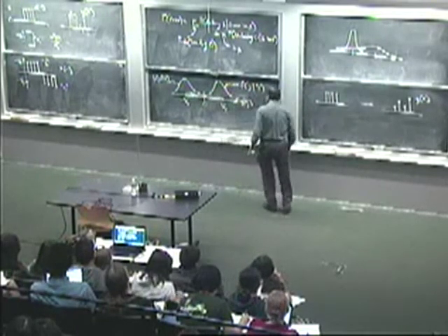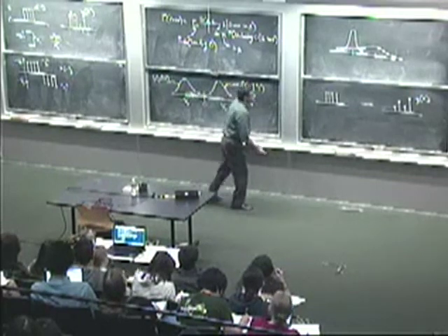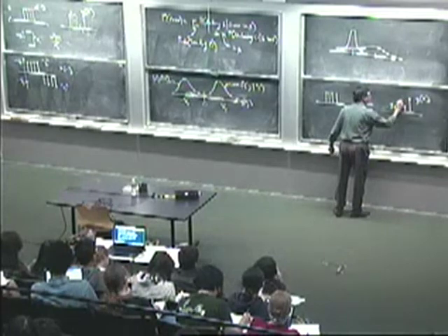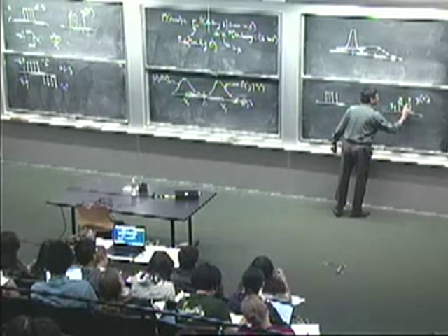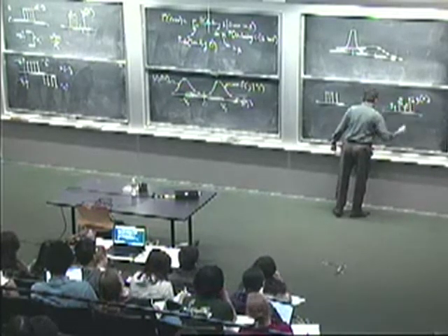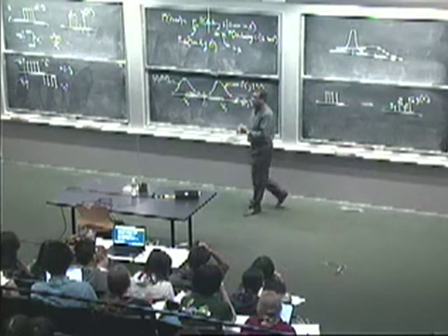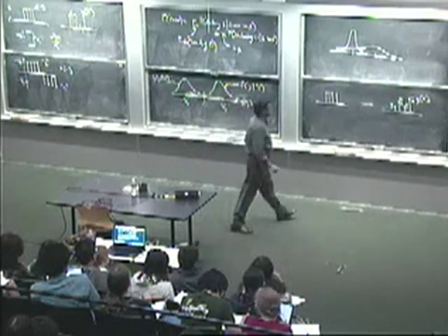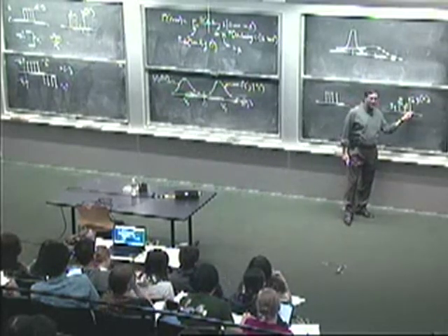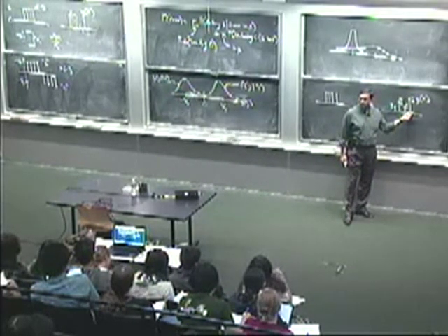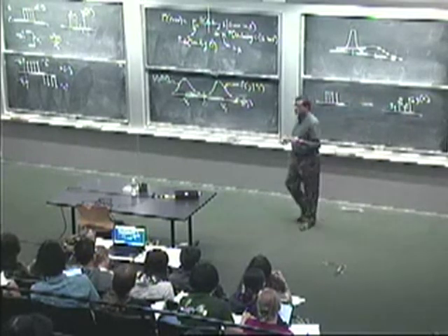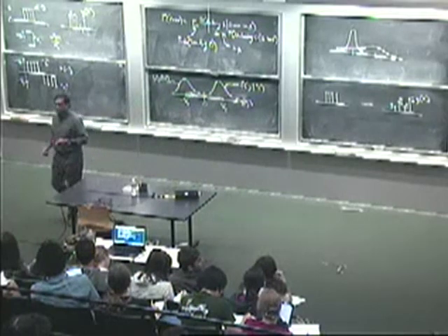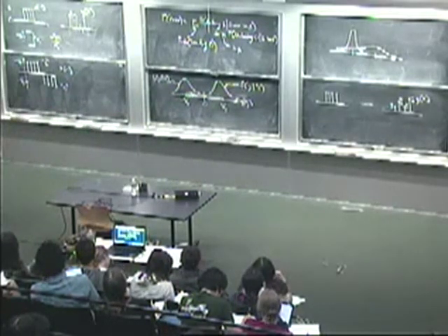I've got some amount of noise adding into all of these samples. So there's some standard deviation's worth on each of these. Which is the most trustworthy sample here? Yeah, it's the one on the right because it's got the largest amplitude. By itself, it has the largest signal-to-noise ratio. So if you're going to combine these samples, you would think that you would want to put more weight on the sample that was larger. So you can actually formulate that analytically.